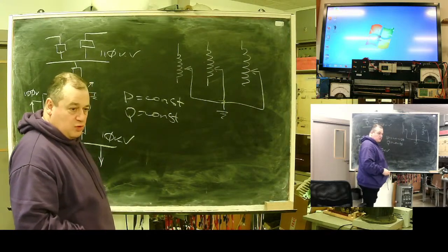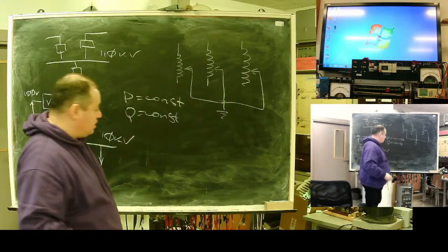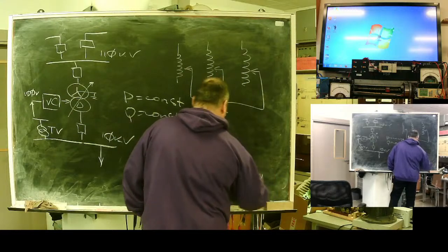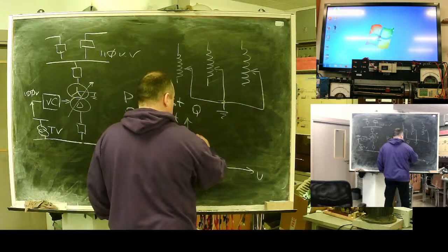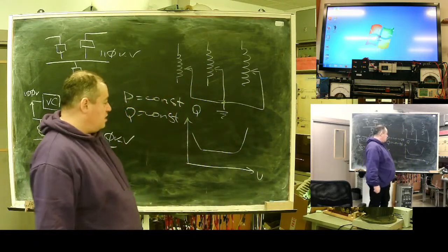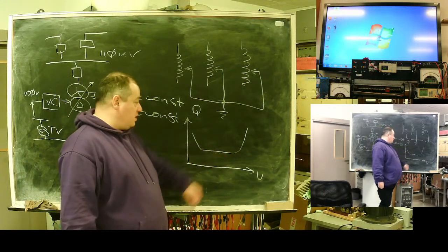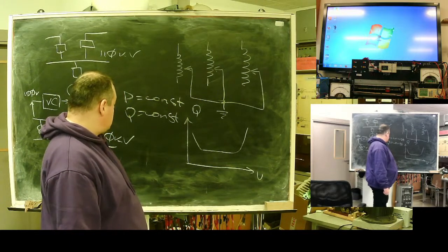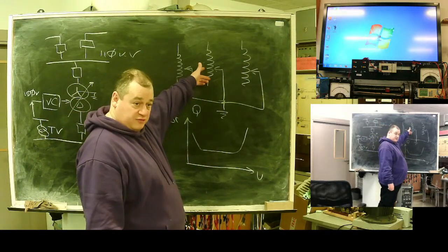In more detailed look, we need to take into account limits of regulation. We may see, for example, voltage, reactive power looks flat and again rises. And this flat area is determined by the range of control transformer.